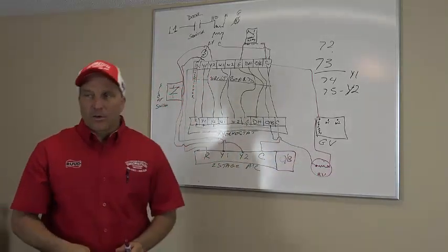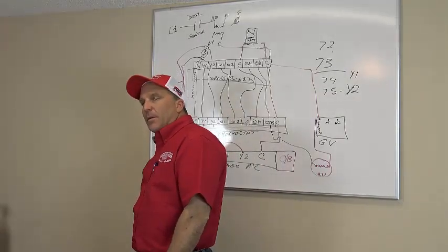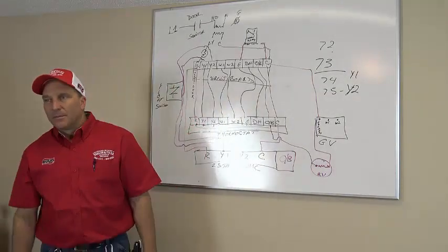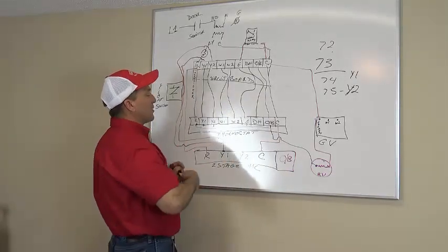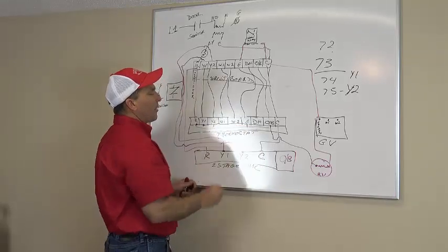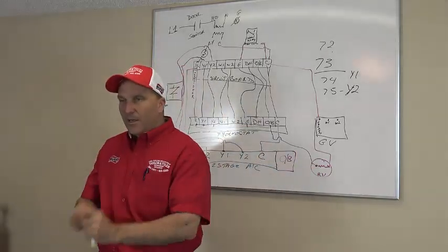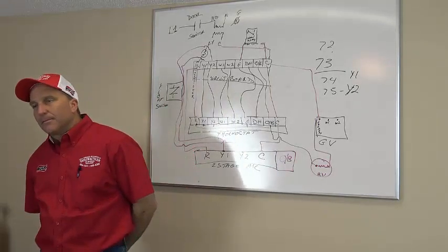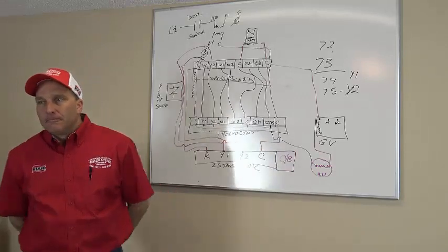So right now, so far, all you've done is energize the reversing valve. Tell me what else happens. Oh, and G. Okay, so G is going to energize too, right? So far your reversing valve is energized and your fan motor's running. Are you getting any heat now? In your furnace. Your W1.